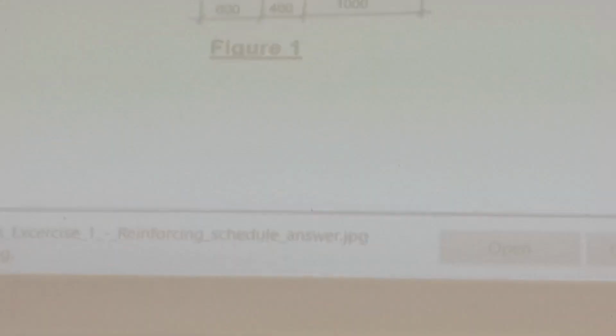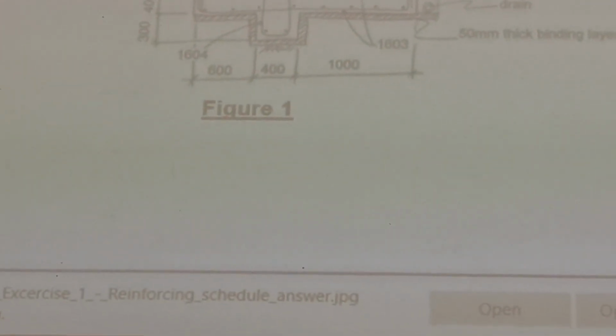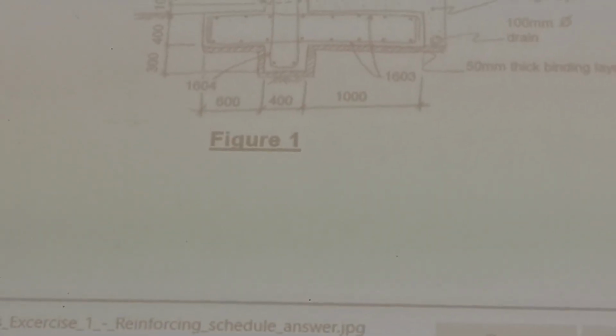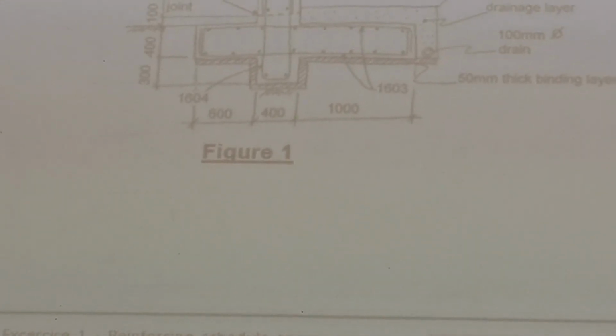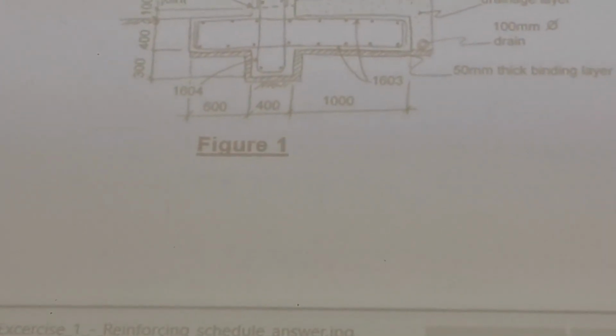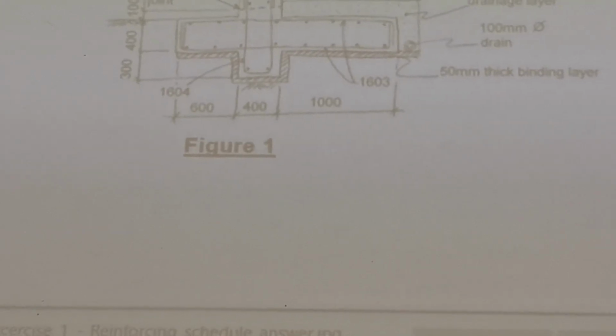The width of this is going to be equal to, if you have a look at the bottom, it says 400. So it'll be 400 minus the 250s either side is 300. You add all that up, then you take off your beam allowance of 36, and you end up with 2.768. Right? Now that was only half of what you're expected to do in 50 minutes in the exam. The other half was the quantities, which you have to do for me for the assignment.